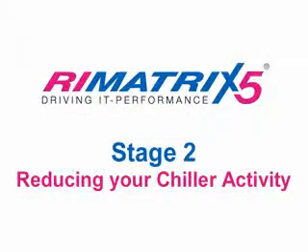Stage 2. Reducing your chiller activity. As mentioned before, the chiller produces the cold water for the CRAC system. It effectively uses a compressor and a refrigerant. The majority of your energy costs when cooling your data center is attributed to the compressor. Minimizing its activity is crucial for energy efficiency, and a simple way to achieve this is via free cooling.